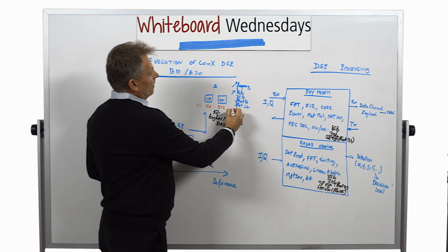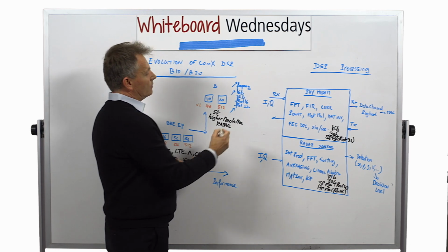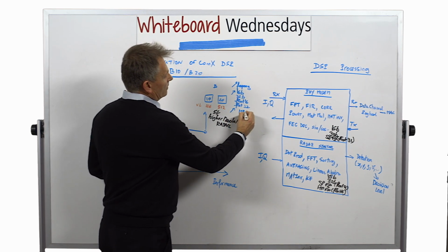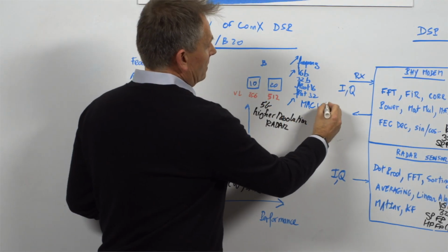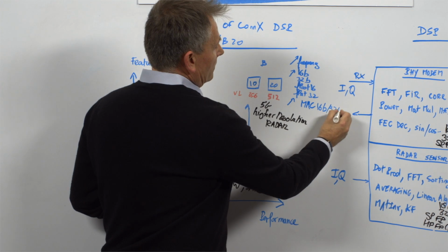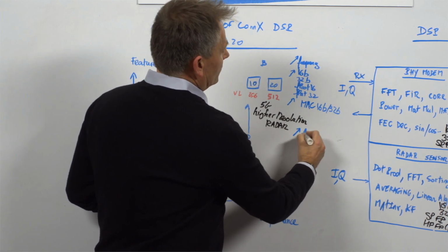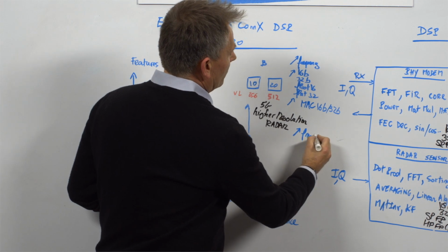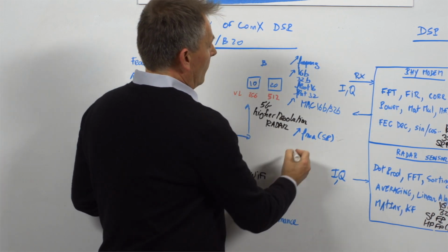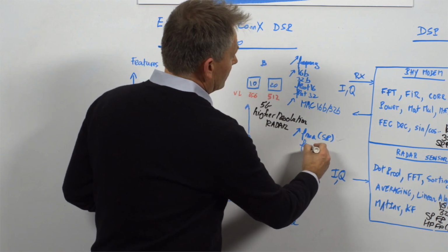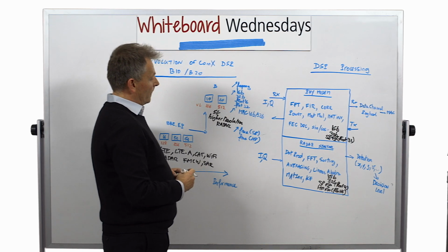We are also adding more capabilities in terms of processing elements for the MAC. So in that particular case, it's multiply accumulate for 16-bit and 32-bit data types. But also additional floating point capabilities with more FMAs for the single precision floating point, but also more FMAs for the half precision capabilities.